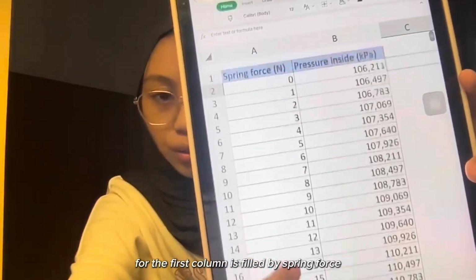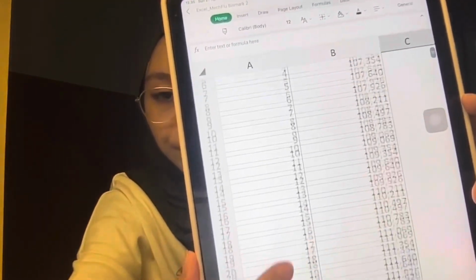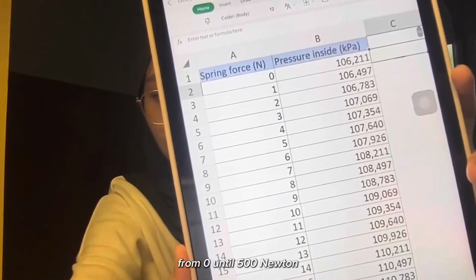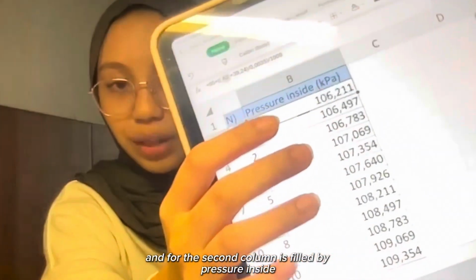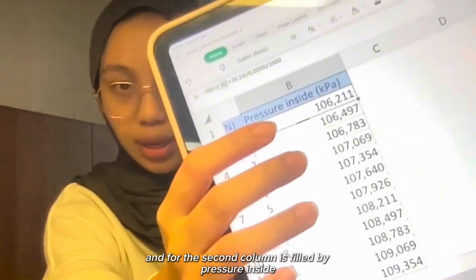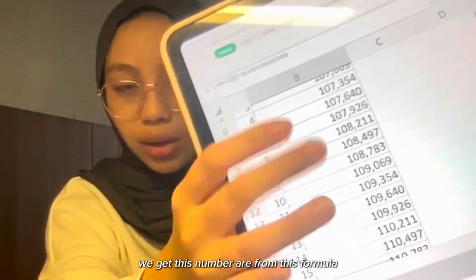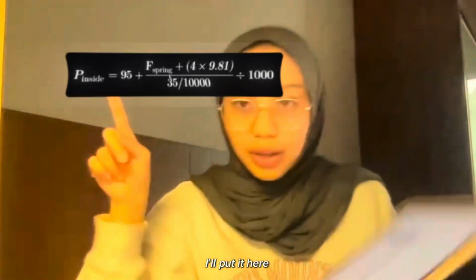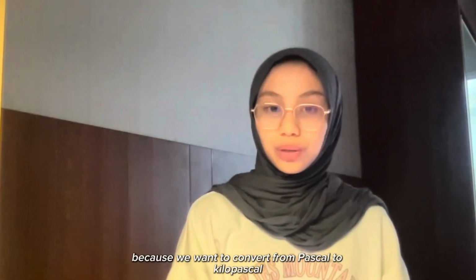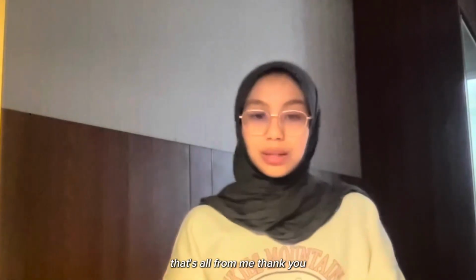Okay, so for number 6, we use Excel. The first column is filled with the spring force from 0 until 500 Newtons, and the second column is filled with the pressure inside in kilopascal units. We got these numbers from this formula, and it is divided by 1000 because we want to convert from Pascal to kilopascal. That's all from me. Thank you.